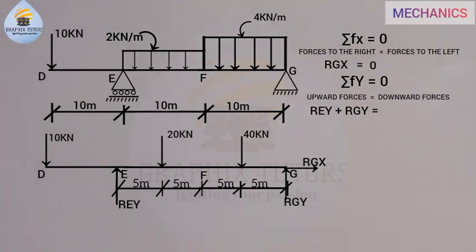So you're going to put them on this other side for downward force. So it will be 10 plus 20 plus 40 because they are all facing down. That's why I'm adding them together. Now we will say that REY plus RGY will be equal to what? 70 kilonewton, which is as a result of 10 plus 20 plus 40. So we are going to term that equation 1.